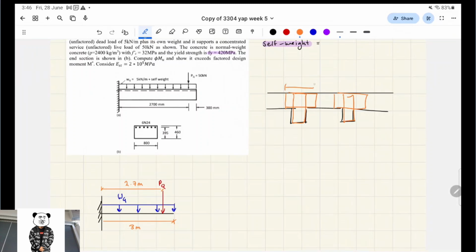So this turns out to be a value we call bEF, the effective flange width, right? And so that shape ends up being a T-beam. Even though it's not the most optimal shape, you see it a lot in practice. And so they have to teach you it in this core concrete course because it's just everywhere, I guess, in structural design.